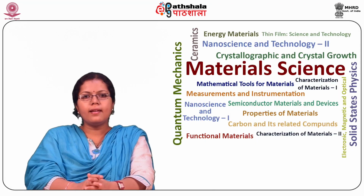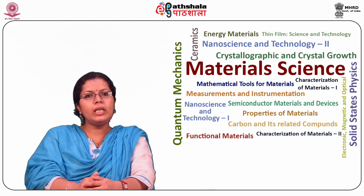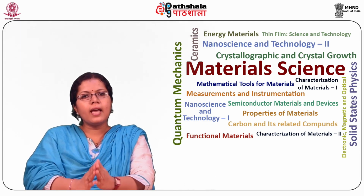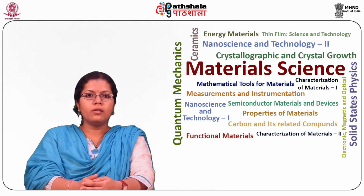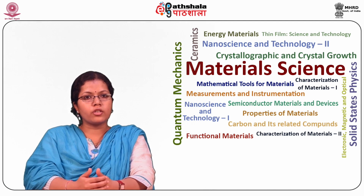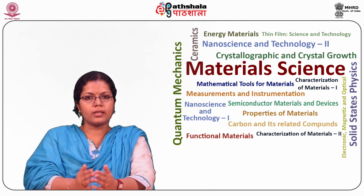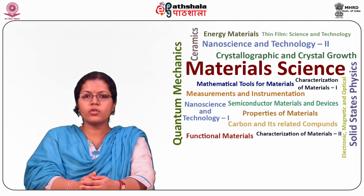So students, let us summarize what we have learned in this module. We learned about the analog ammeters and voltmeters. We saw that the essential requirements of a measuring instrument are: first, that its introduction into the circuit where measurements are to be made does not alter the circuit conditions. Second, the power consumed by them for their operation should be small.